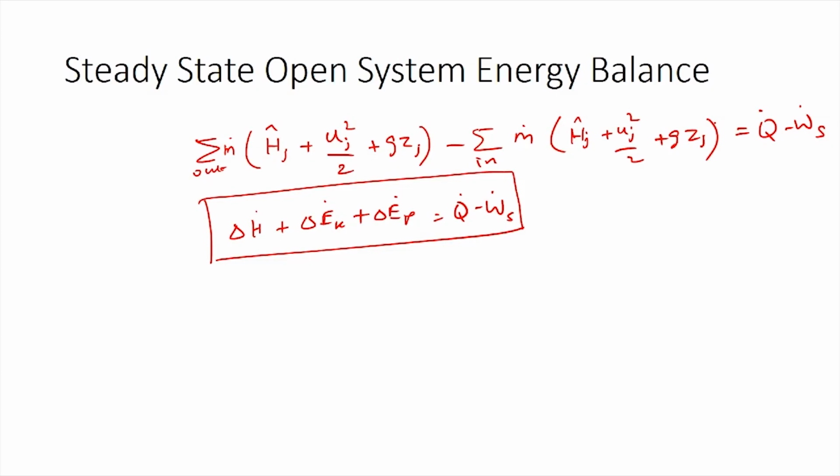What we need to understand here is, for a closed system energy balances are performed using internal energy, and for open systems energy balances are performed using enthalpy. This is because the flow work associated with the flow of a material in and out of the system is accounted for by using enthalpy. So, internal energy plus this flow work ends up becoming enthalpy in the mathematical expression. Therefore, we use enthalpy instead of internal energy while we perform energy balance calculations for an open system.